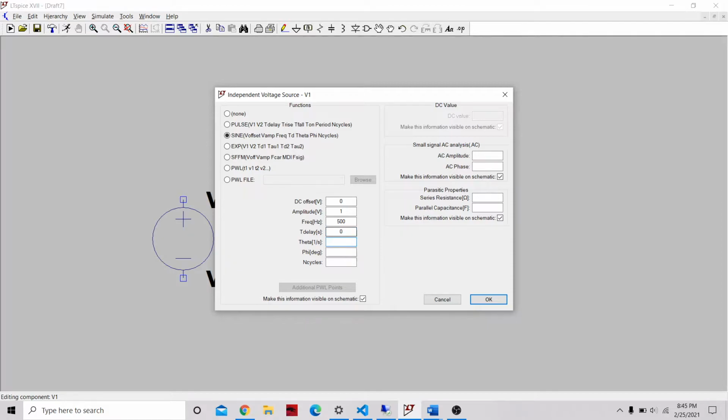If we wanted to have this be a sine function, we can just have this be a 0. If we wanted this to be a cosine, we put in 90 degrees here. Oh, my apologies. I confused the theta with the phi. The phi is our phase shift, so 0 for sinusoids and 90 degrees for a cosine.